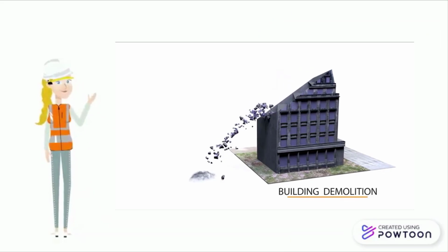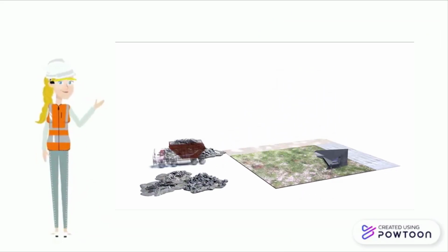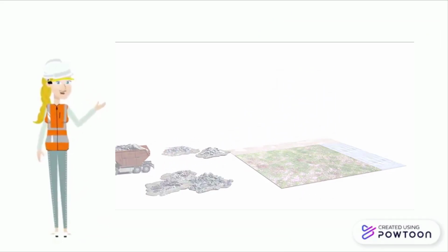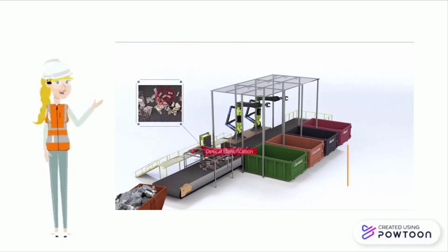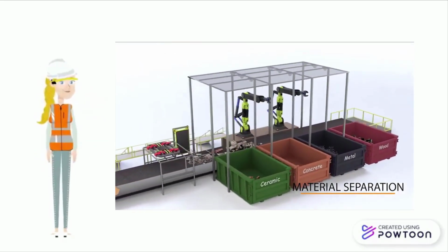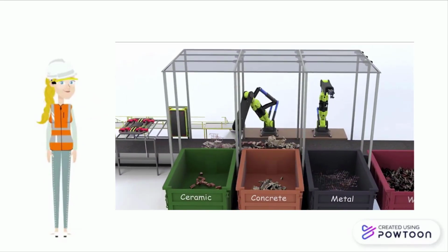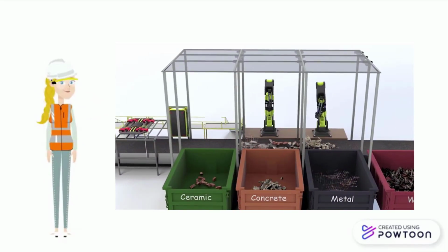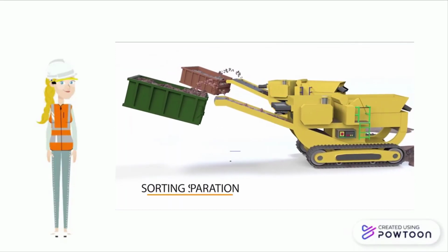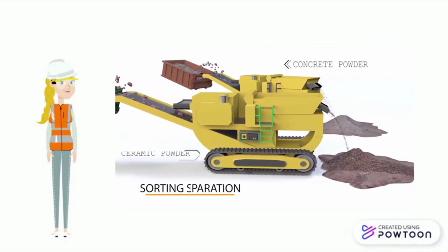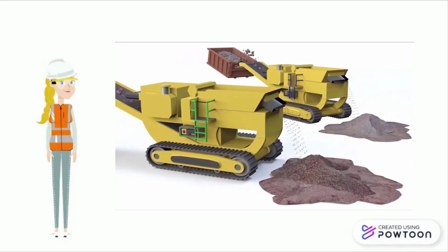This video shows how demolition waste can be recycled. Concrete and brick can be recycled by crushing it into rubble. Once sorted, screened, and contaminants are removed, reclaimed concrete or brick can be used in concrete aggregate, fill, road base, or riprap. Mobile concrete crushers also allow for recycling of concrete on-site.